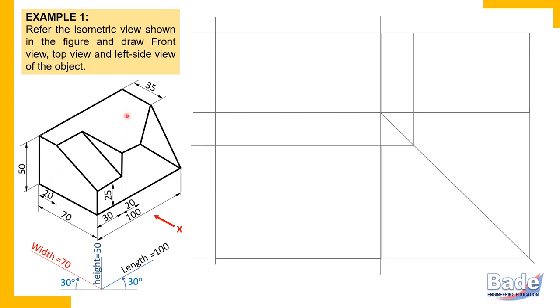Now listen, if a surface is parallel to HP, you may use a thin book, keep it parallel to the ground, parallel to the floor, and check. In the top view, it gives its true shape, but in the other two views, it appears as a line.